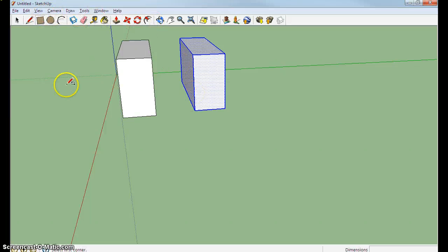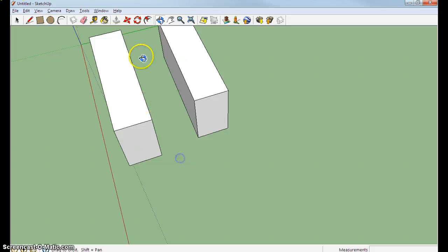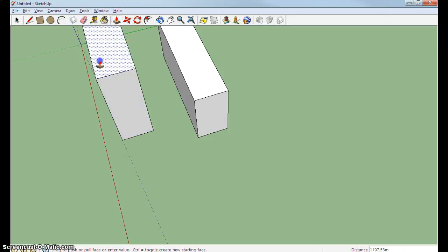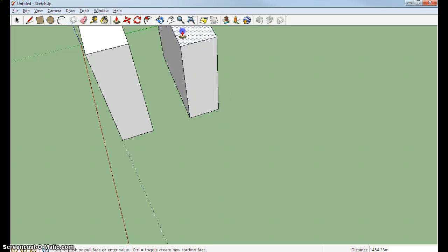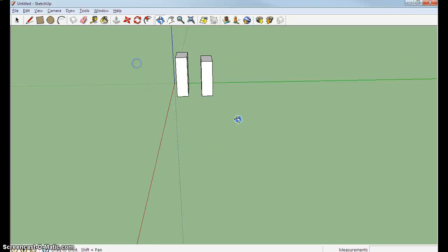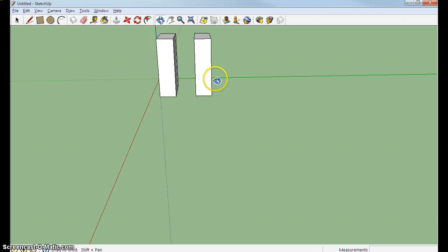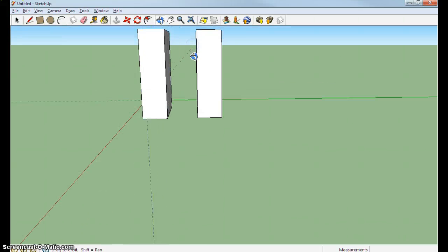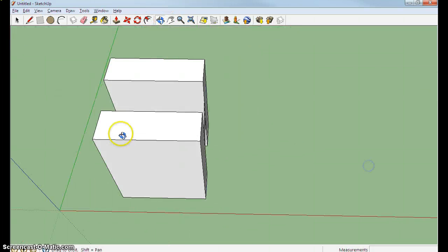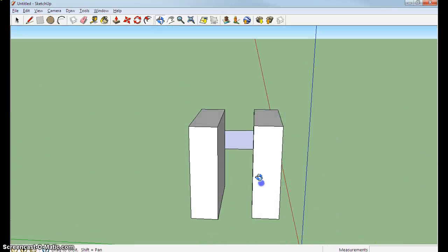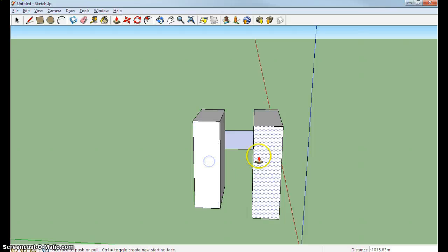And then what I did, I used the rectangular tool. You just use the push tool, and just push this and pull this, push this and pull this. So there we go. You guys might be thinking it's the work of a pencil tool, but no, this is not the work of the pencil tool. This is the work of the rectangular tool, which we use like that. As beginners, you have to think that. Okay, you don't want this so thick, so I'm just going to adjust, and that was fine. You just use this and it becomes 3D.